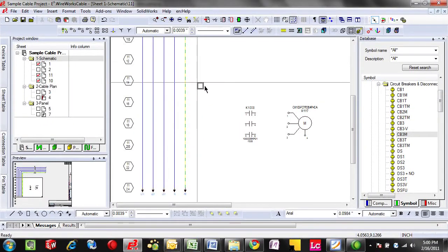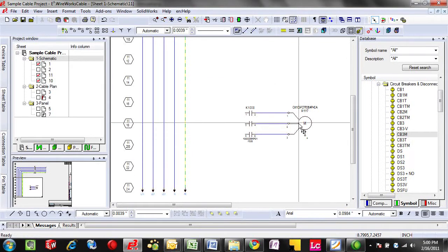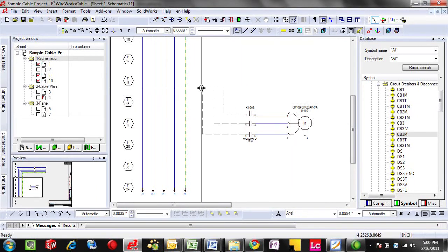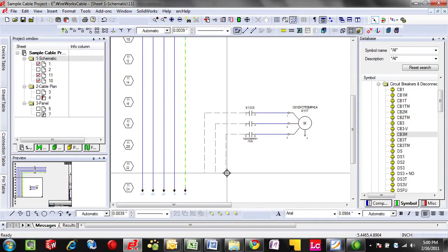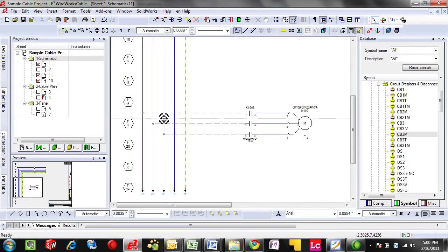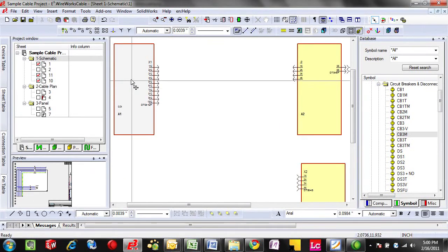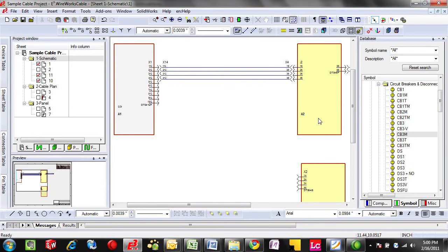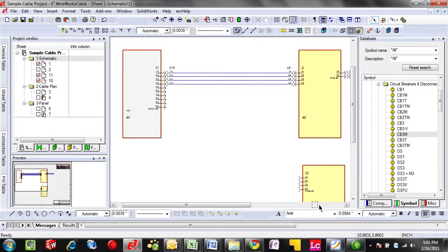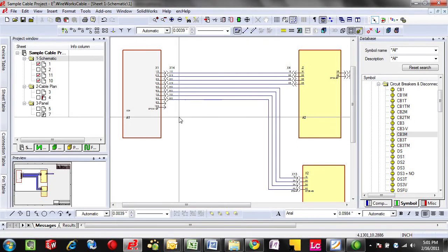Speed up creating these connections, such as a horizontal box connection, which will connect anything horizontally. We can also do a group selection, which allows us to go and bend corners with multiple selections, or stagger devices if we want to connect into something like a three-phase power. When working with system interconnections, such as cabling, that horizontal connection will automatically put the appropriate matching connector. In a similar fashion, we can use that group selection, can even invert the selection if we like, or leave it staggered, and can go and interconnect with another system.